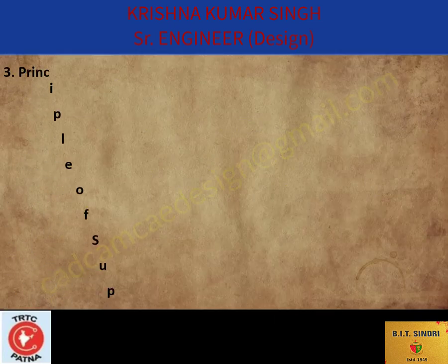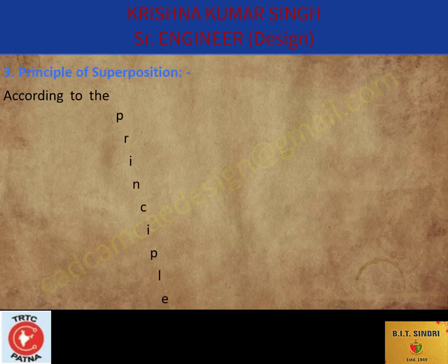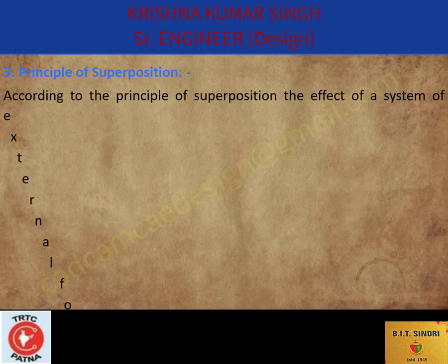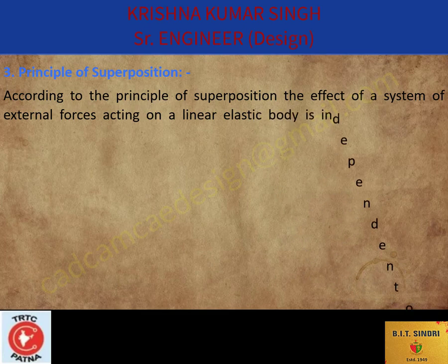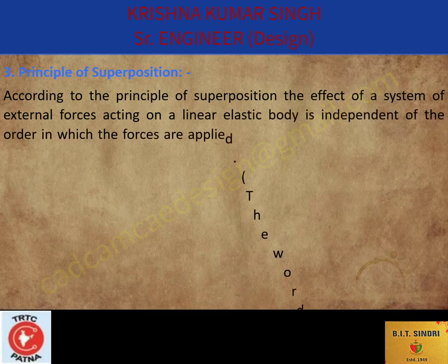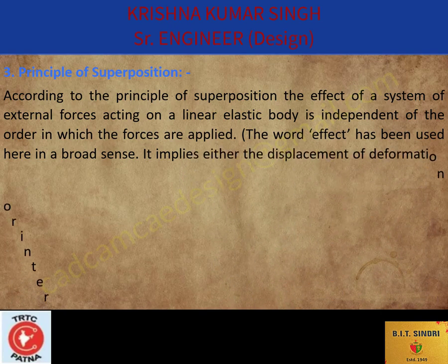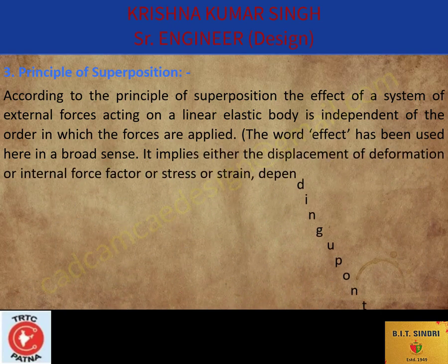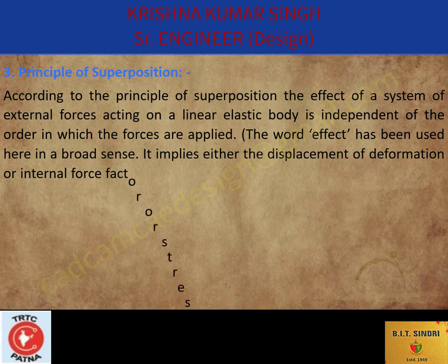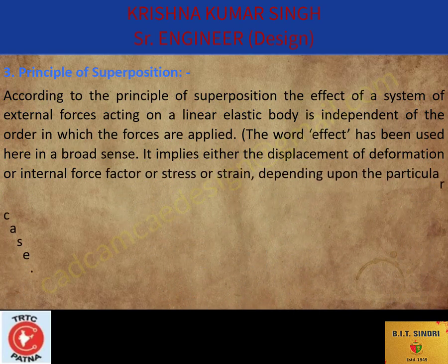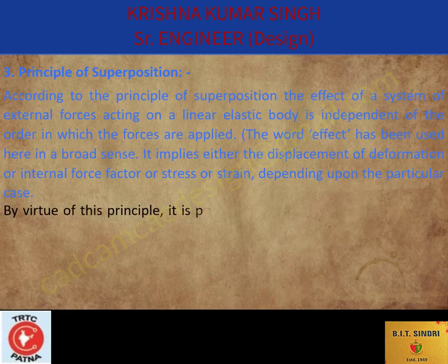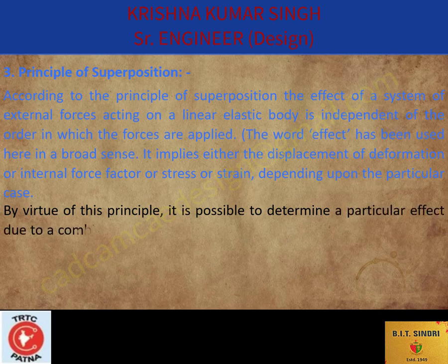The next is your principle of superposition. According to the principle of superposition, the effect of a system of external forces acting on a linear elastic body is independent of the order in which the forces are applied. The word effects has been used here in a broad sense. It implies either the displacement or deformations or internal force factor or a stress or a strain depending upon the particular cases. By virtue of this principle, it is possible to determine a particular effect due to a combination of loading by considering the